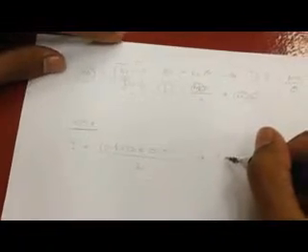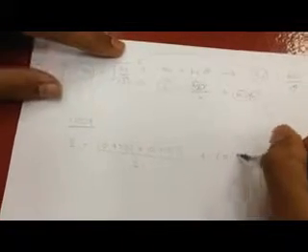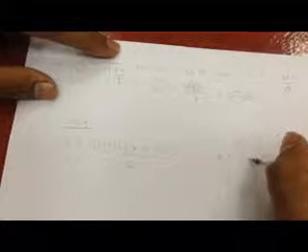So we are going to use 0.1 kilogram times 0.002 as the height squared. So the value here is 5.2977 times 10 to the power of negative 4. So this is the value of I. And now for the natural frequency we're going to use this formula.